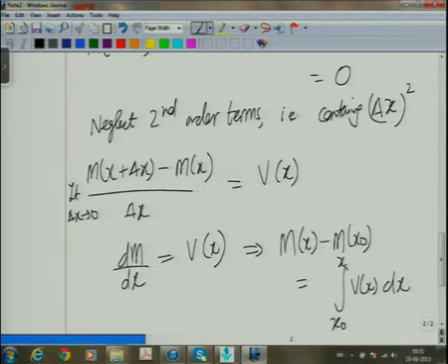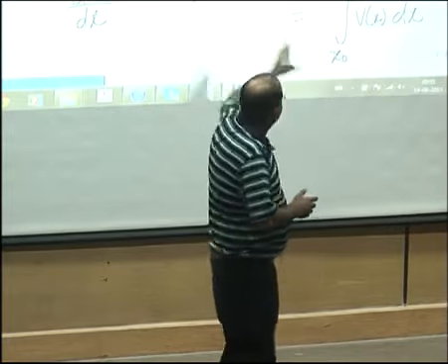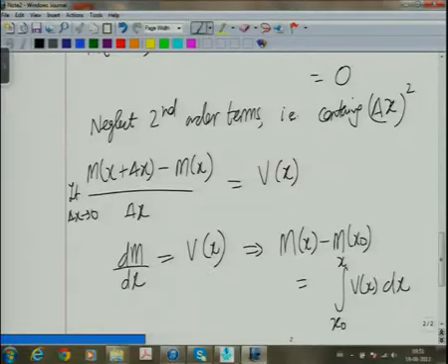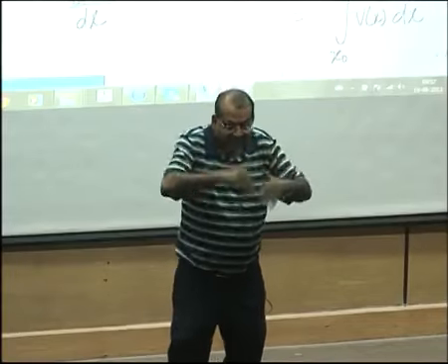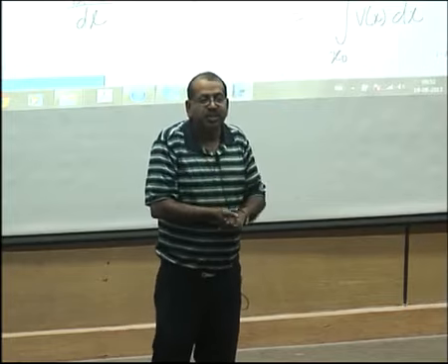Now these two things which we have derived here, one for the loading, one for the shear force, one for the moments, as formulas we may not use them, but they are useful in their physical interpretation, because what this tells us is that a change in the moment, bending moment between 2 points will be equal to the area under the shear force curve between those 2 points. So if we have drawn the shear force curve, then the area under the shear force curve will give us the value by which the bending moment changes between these 2 points.